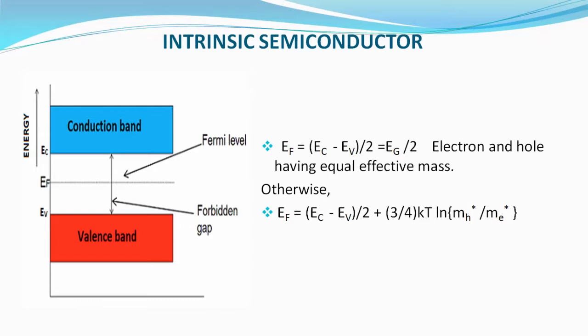So if we adjust this internal force, and consider only the external force, and consider the acceleration is due to the external force only, by neglecting that internal force and adjusting the internal force in with the mass of electron or holes even, that is called effective mass. That means effective mass is also the mass of electron or hole by adjusting the internal force there. So that is effective mass.